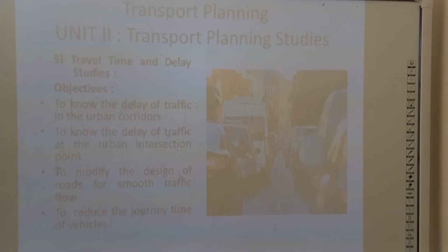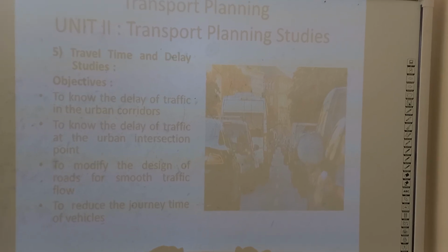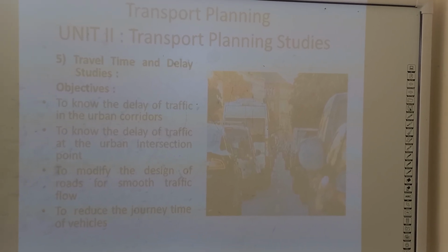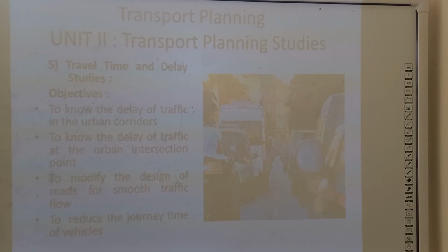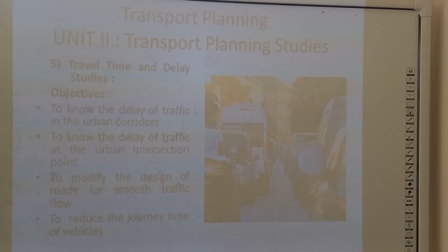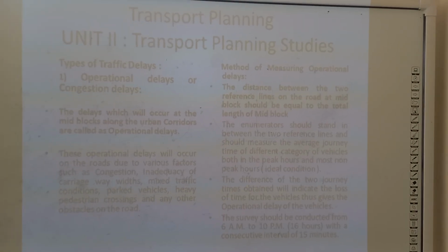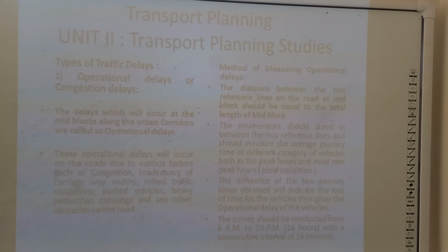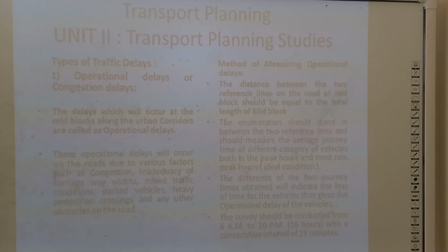Coming to the travel time and delay studies, very important because as far as possible on urban roads, travel time should be less between origin and destination. Hence the delay should be less. We have to calculate both operational delay and fixed delay. Operational delay means delay which is occurring at the mid block. Fixed delay is delay which is occurring at the intersection point.